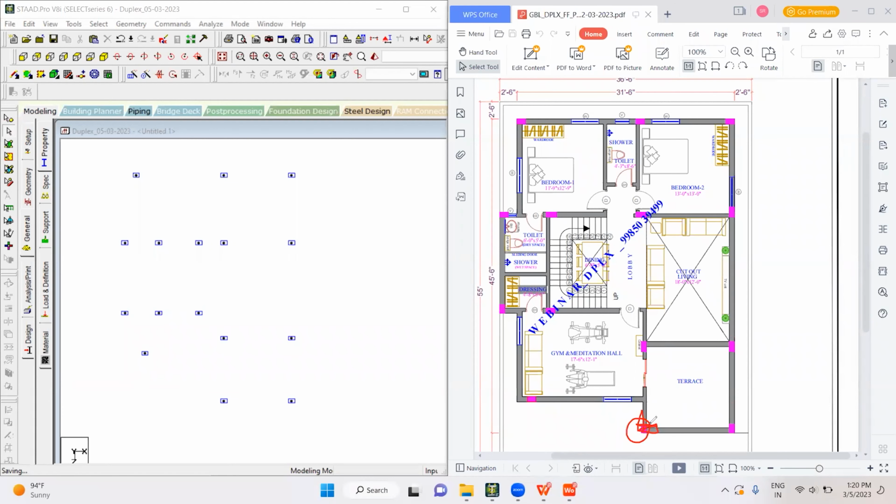But if we are keeping a door here, we are indirectly wasting this space, right? Because we have a column here, we need to keep an additional layer of brick wall and then start connecting this door to it. So to use even 3 or 4 inches of space, we can change its orientation, and we can use our space very effectively. So that's 1, 2, 3, 4, 5, and then 6, right? Technically speaking, you can change the orientation for all of them. If we keep this orientation like this, then you'll have enough space for a ventilator also, right? So I'm going to change this also.